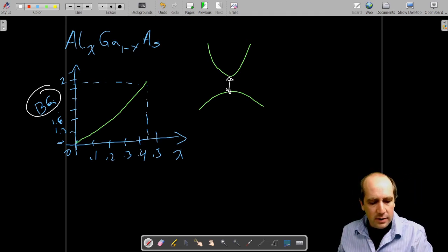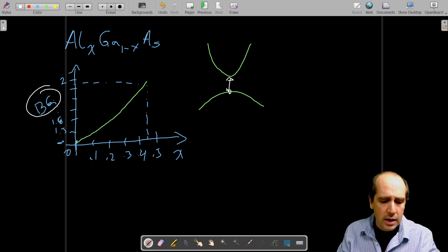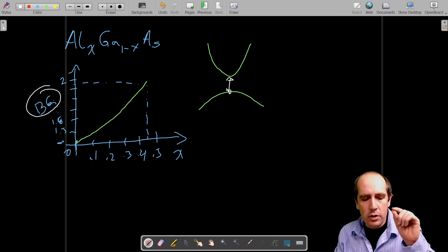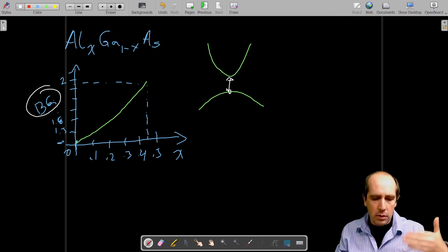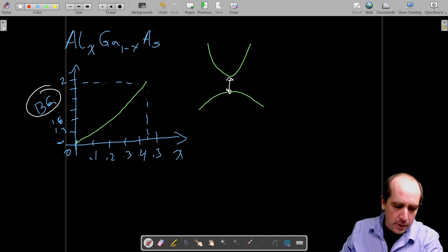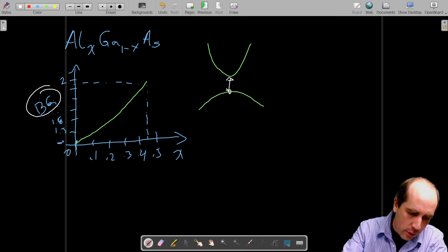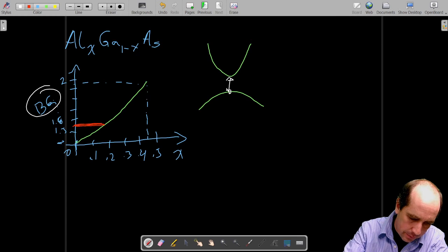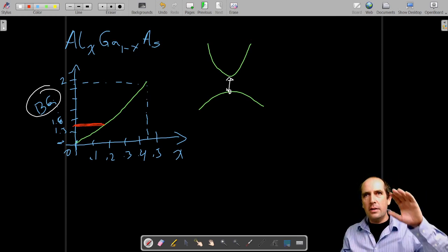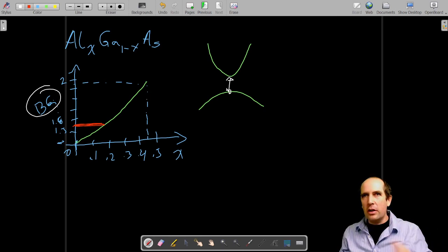So this opens the possibility of creating semiconductors that have a band gap that is tunable, that you can pick, you can choose energies in this region. So 1.55 or so, somewhere around here, just for reference, is where the red color starts. Below there is infrared. You can hardly see it.